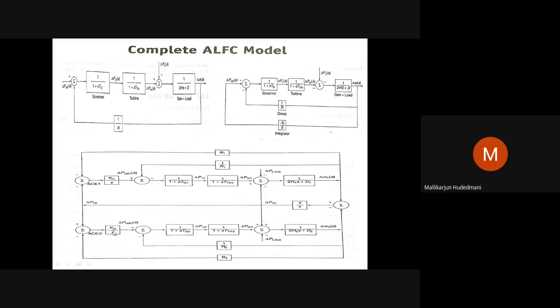Then that is multiplied by a gain constant and integrated to give you a change in reference point, if required. It means this integral controller will respond if required. Otherwise, it will always be in a stop condition. Stop means not changing the point. The point is static. If there exists a requirement, the integral controller will change the reference point, else it will be static. We say integral is off when this point is not altered. If it is on, it is trying to modify this. That is the meaning of the integral controller in action in steady state.